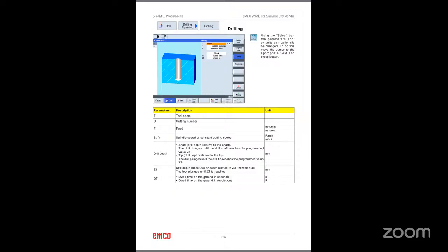Then how much distance the tool will go into the workpiece? So this much distance, say 20. I will change this to 20. And the tool will dwell there 1 second. Click accept. After centering, drilling will be happening.